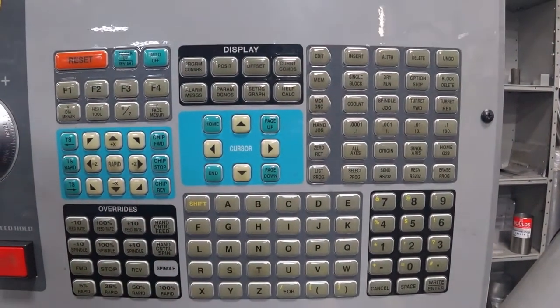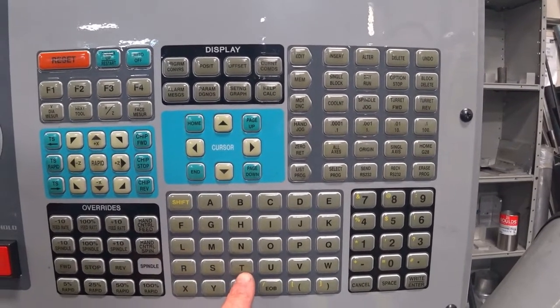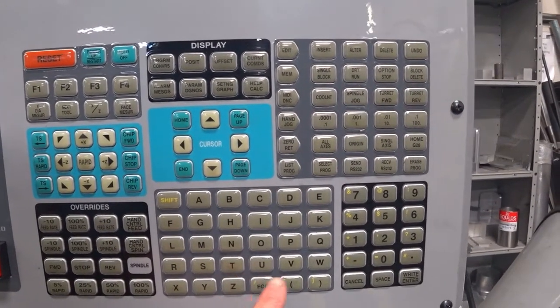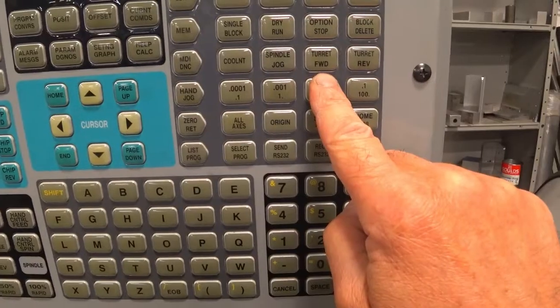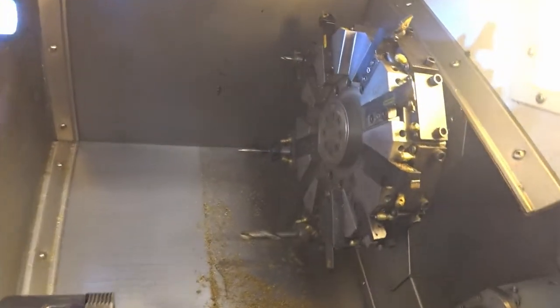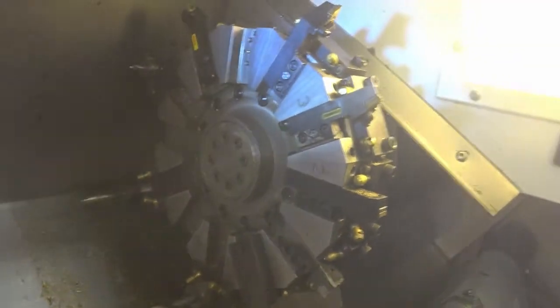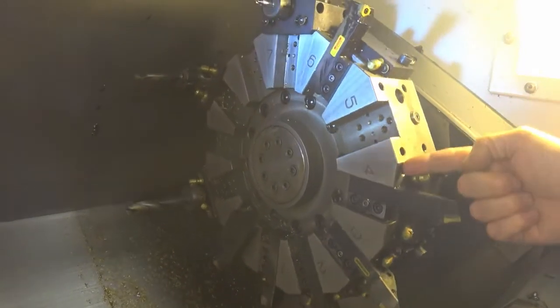Switching now to manual data entry, MDI, for allowing operator inputs to directly command machine functions. Entering a tool address number and cycling the tool carousel by pressing the alphanumeric T4 followed by the ATC key will index the tool carousel to tool 4.